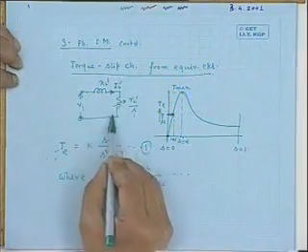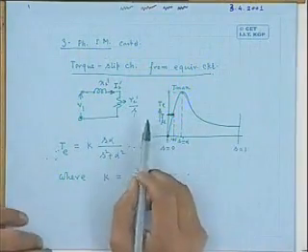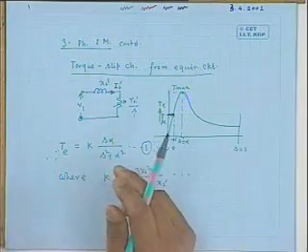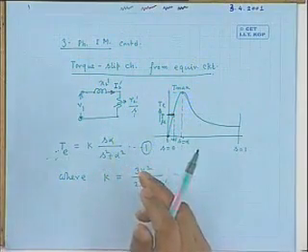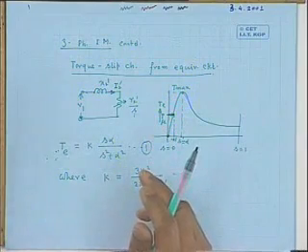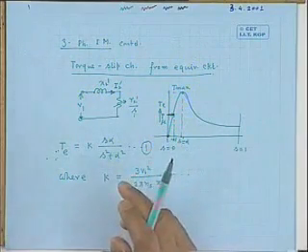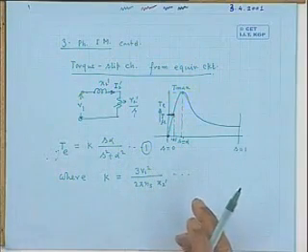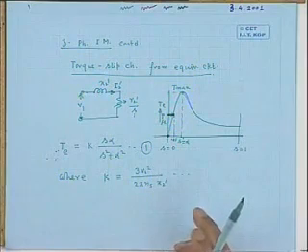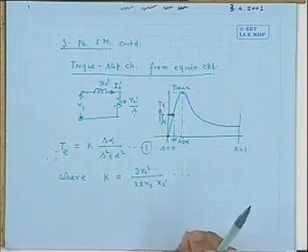Now, if you look at this circuit, air gap power is a measure of torque developed, because it is only divided by a constant, that is 2 pi ns, the synchronous speed, which is constant. So air gap power is a measure of torque developed by the machine, of course in watts.